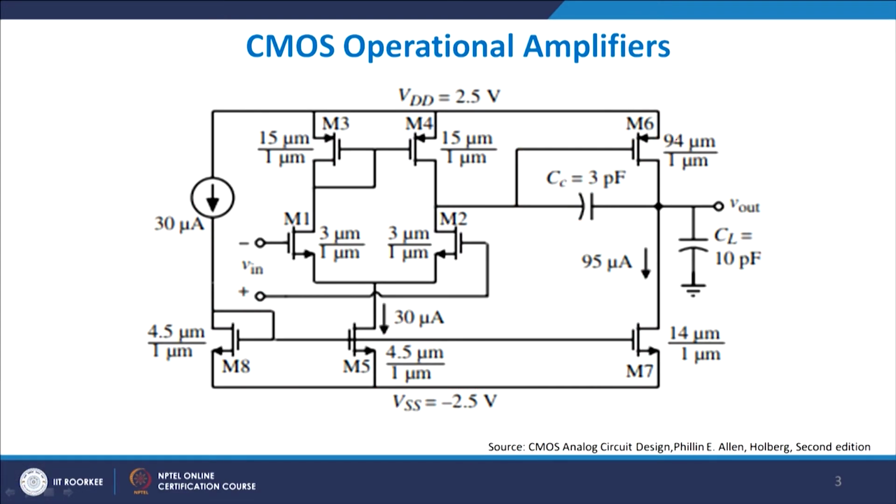working because of two main reasons: you had part 2, which is primarily the differential amplifier part, which gives you a very high gain, and you have part 3, which helps you to give a high swing. So, you have an inverter which pulls your output voltage directly up to VDD, or it goes down to VSS at the bottom. So, part 3, which is this one, helps you to go for high swings, and this is high gain.